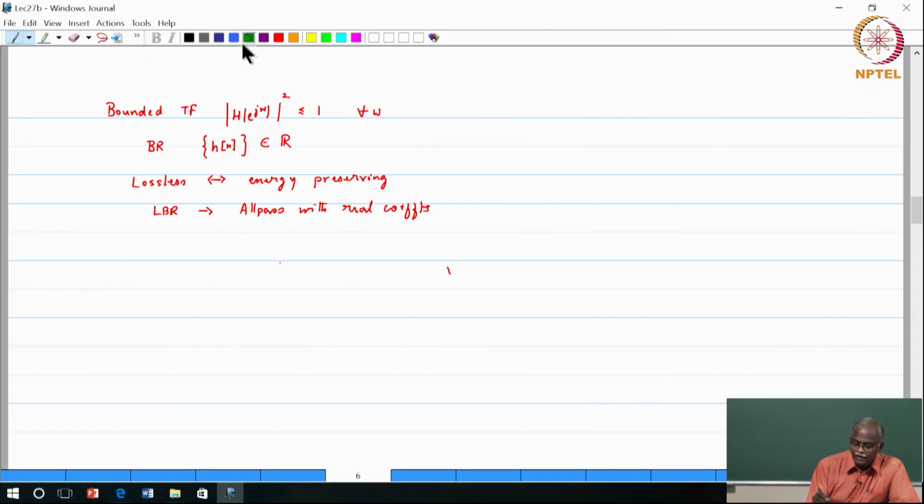We also have another class of functions called power complementary transfer functions. This says that if I take the magnitude squares of these functions or filters, then they add up to 1. Okay, this is a very useful class, as you will see in today's lecture, because this is what actually solves the final problem of perfect reconstruction. Now, it is not necessarily limited to the 2-channel case.